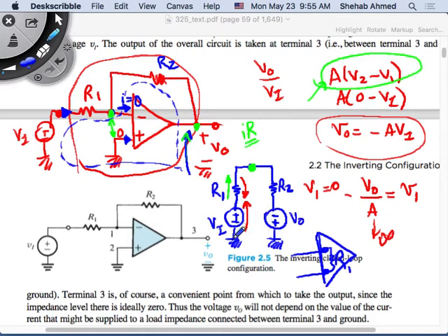That means that current will flow in from your sensor through this R1. It cannot go into the amplifier, right? Where is it going to go? Is it going to go to the ground? No, this is not connected. They're virtually equal to each other. So there's a virtual short circuit between this node and this node, but they're actually physically not connected. So current's not going to flow here, right? The current will not flow here.